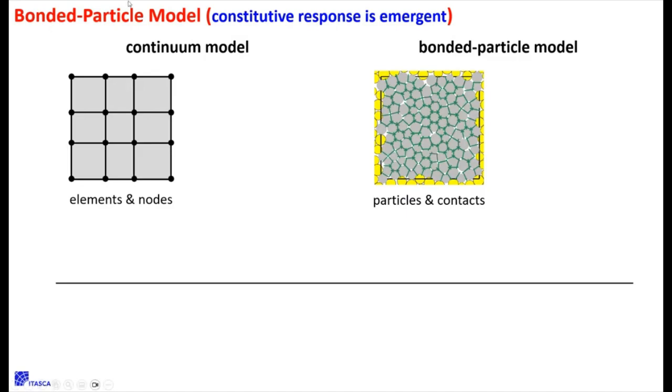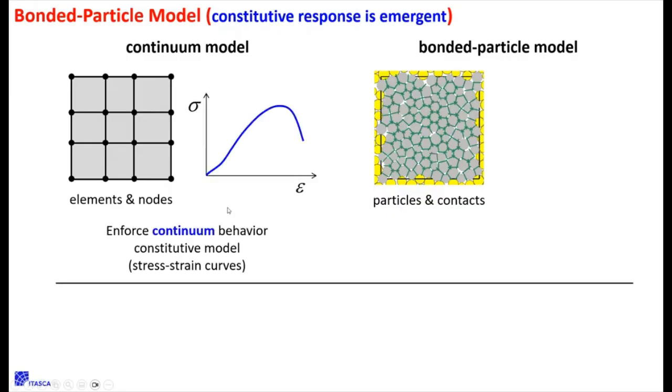And so in this world, the way that we get damage is we put in a constitutive model. This is what we choose. If we want to model a certain rock, we give it a certain curve here. If it's just linear elastic, the curve is simple. It's a straight line, and if you unload it, it goes back to nothing. There's no damage.